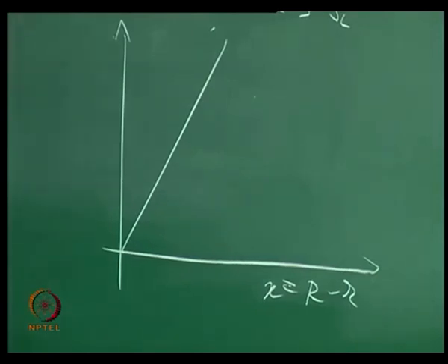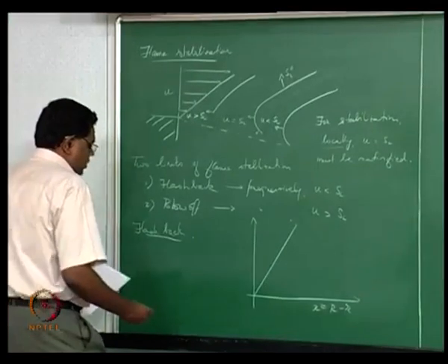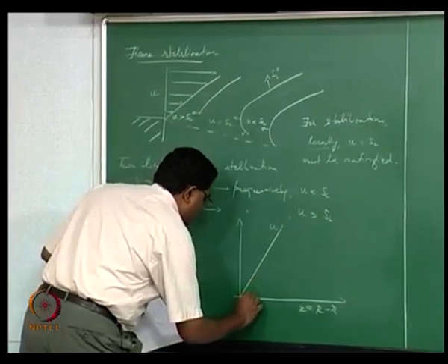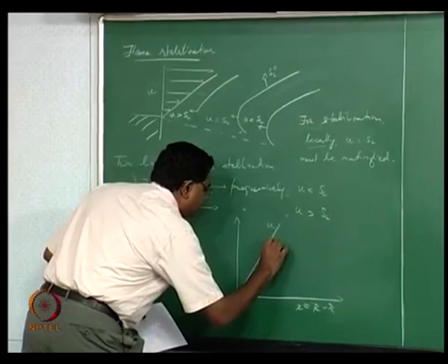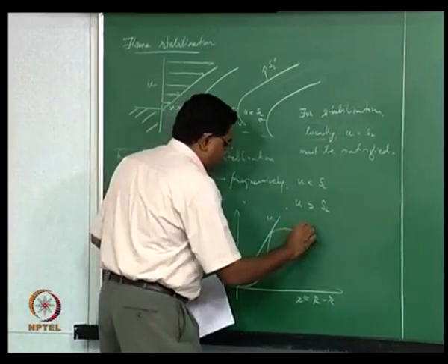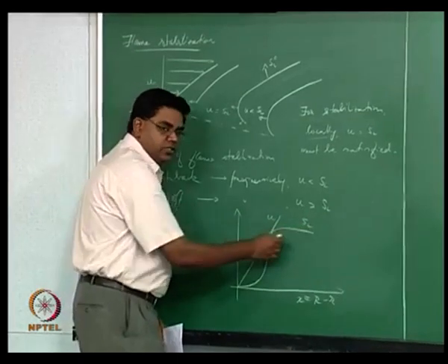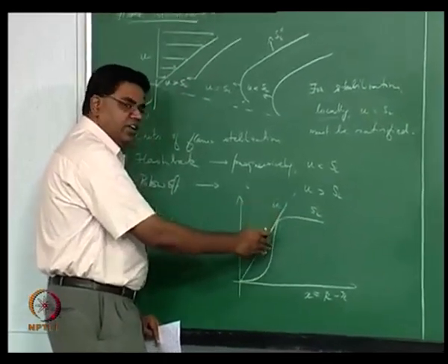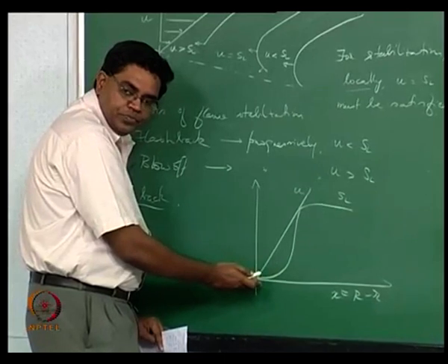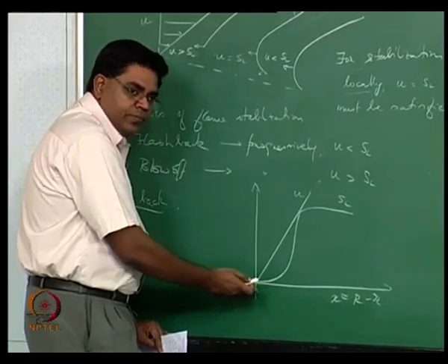What we want to think about is a limit match between u and SL. You see what's going on: the u increases linearly, and the SL for most of the radius of the burner is nearly constant at SL naught, and then it drastically decreases within a short region and goes to 0 ultimately when you reach what's called the flame edge, right.